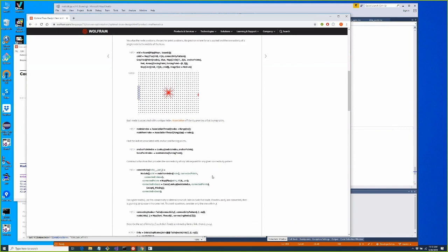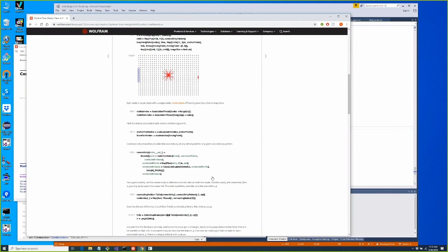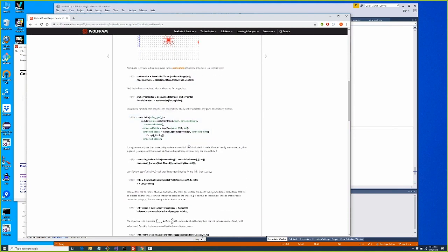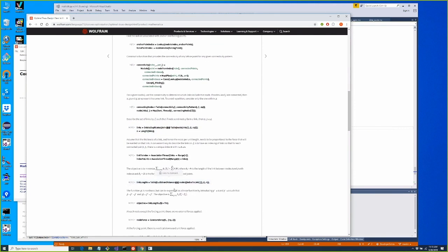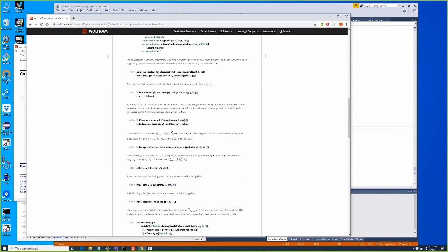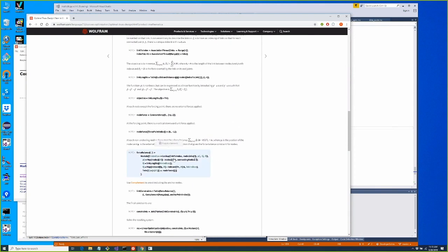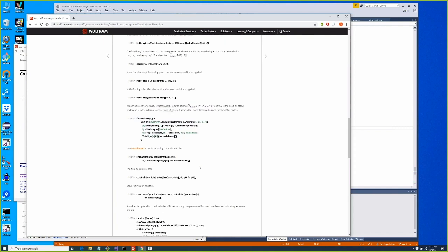Now we set up constraints based on that connectivity. And something we're using here is association to do fast lookup between the actual node and the connected nodes. And eventually we figure out the links. When we do this in a crude way, we get duplicates, so we don't want to add duplicate links as constraints. So we get the links. Eventually, you get a matrix. You put in a force balance equation, so the force has to be balanced.